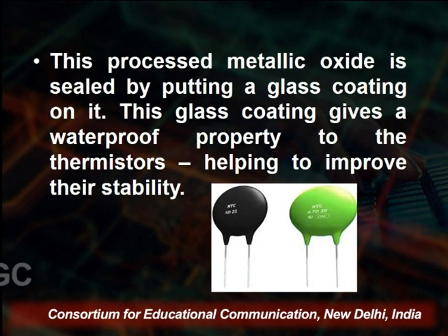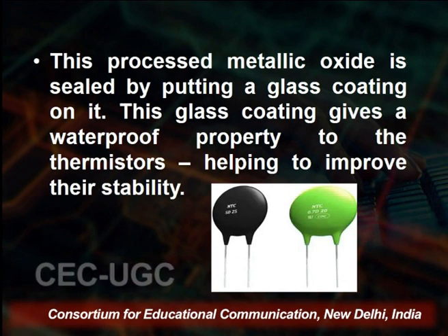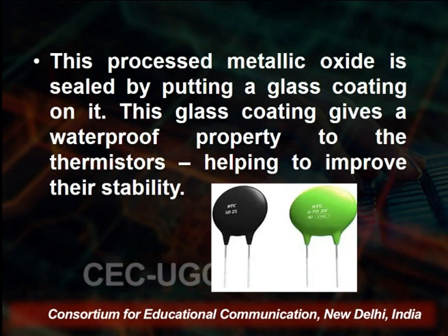In this process, the metallic oxide is sealed by putting a glass coating on it. It is a very thin coating that we put on this slurry. This glass coating gives a waterproof property to the thermistor and helps to improve its stability.